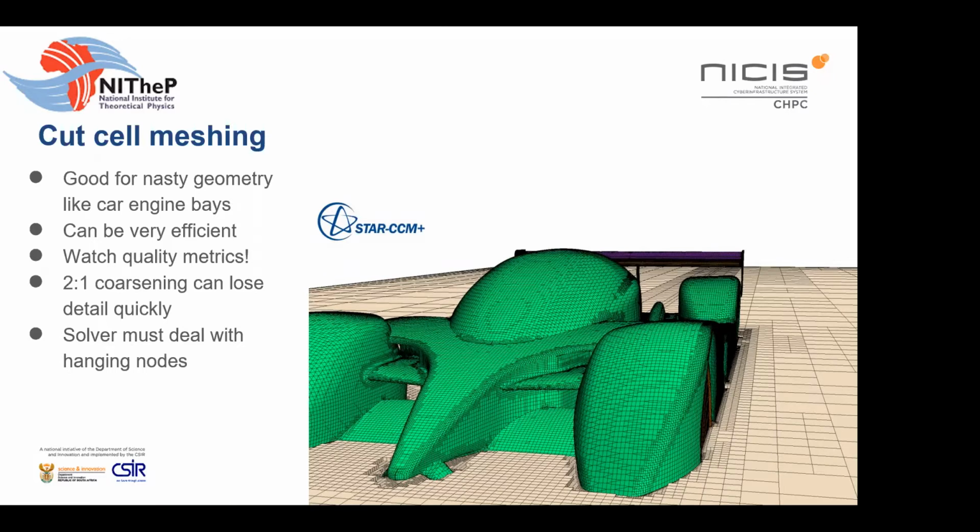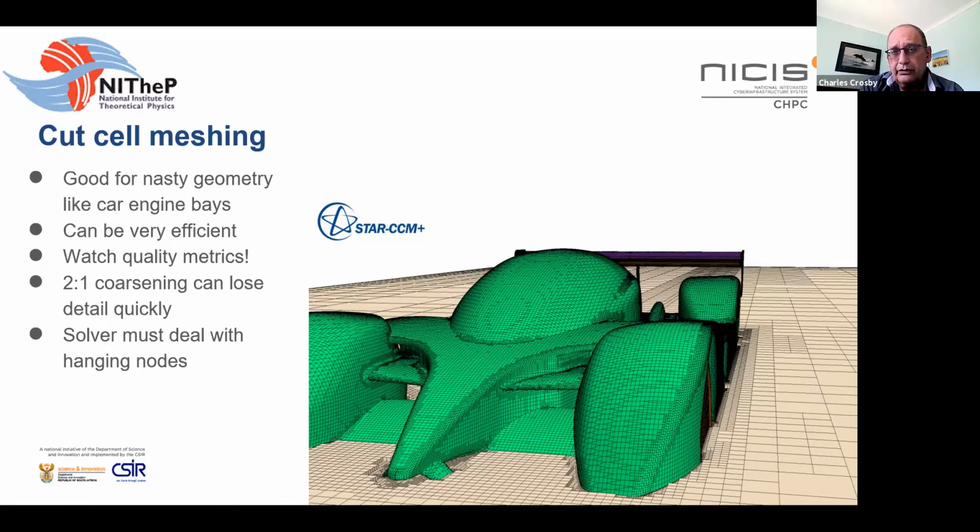Remember I talked earlier about quality control. One of the quality control measures that you need to apply is to check what influence your grid has on the results. So there are lots of other things that can affect the quality of your results, but the grid's very important. And a standard method is to keep refining your grid, make your grid smaller and smaller, which means your solutions take longer and longer, and map out the change in the results that you get with this increasing refinement. So under certain conditions, it'll be a clear asymptotic relationship and it'll flatten off, and you know that's fine enough. There's no point in going finer than that.